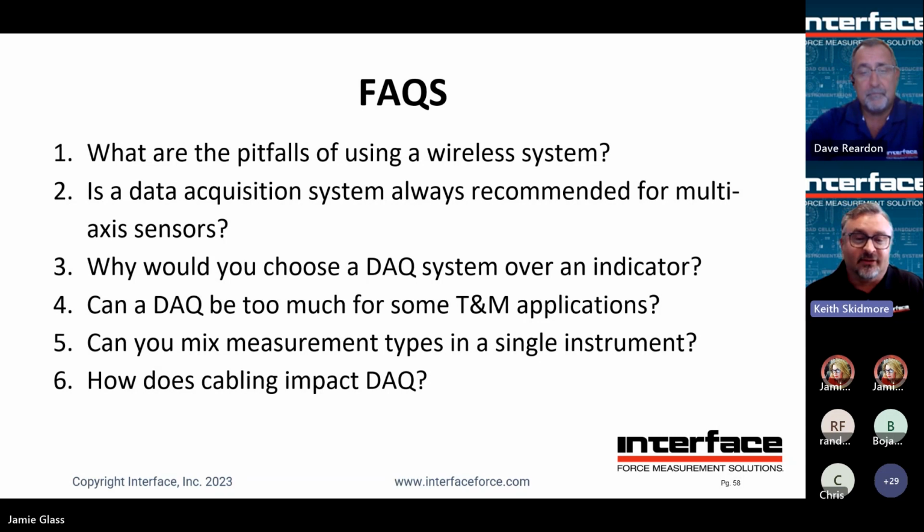The cabling is not a factor unless somebody decides to cut the cable and change lengths or whatnot. So yes, cabling definitely needs to be considered. Shielding, proper grounding, all of that goes into a good measurement system.